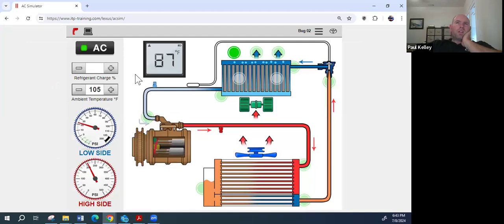Right, so you can come over here. If you guys would like, you can shoot that temperature gun all over the place and measure all sorts of stuff, but really we are pretty decent. Other than the thing to point out is even the evaporator core itself starts out cold, gets a little warmer, warmer, and then it's pretty warm by the time it's coming out of the evaporator. To be quite honest with you, that's actually all you need if you really understand AC to diagnose it. However, we'll go a little step further.